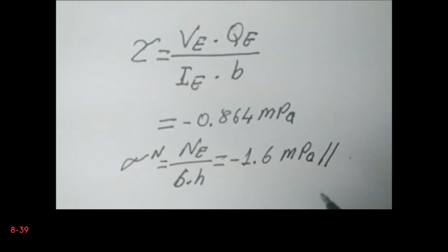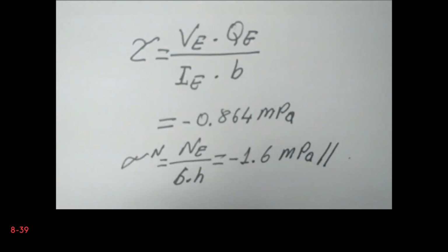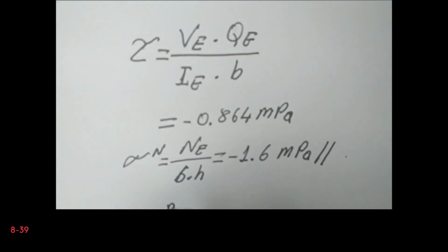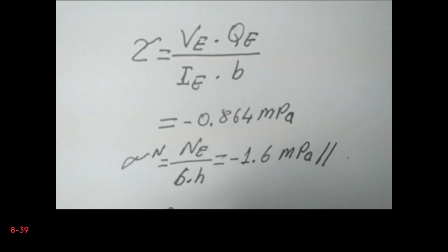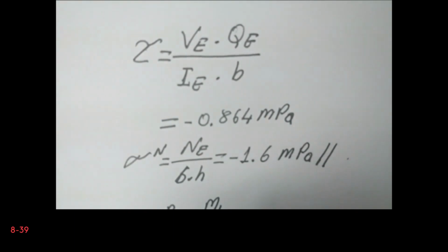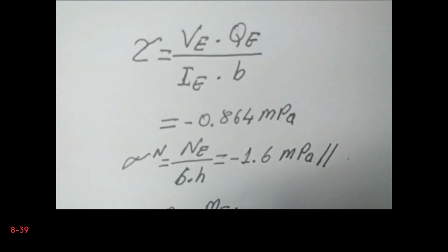Then we have the stress due to the bending. That is minus ME multiplied by the distance to the centroid, that is minus DE, divided by IE.